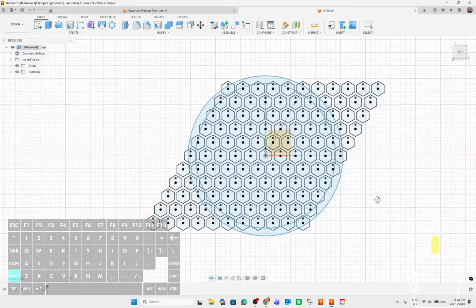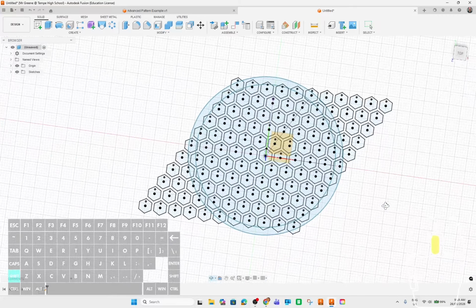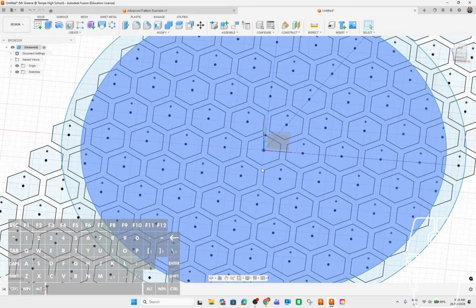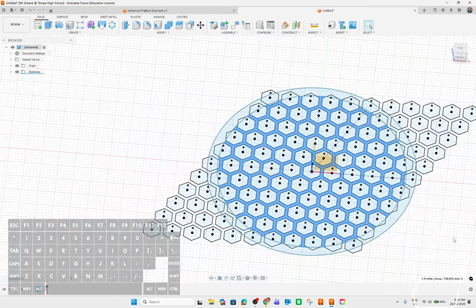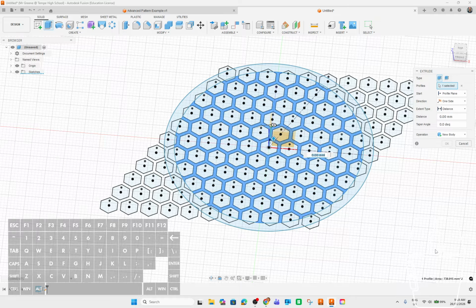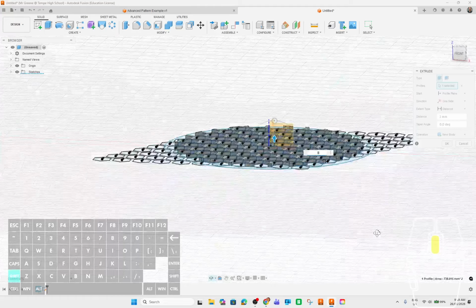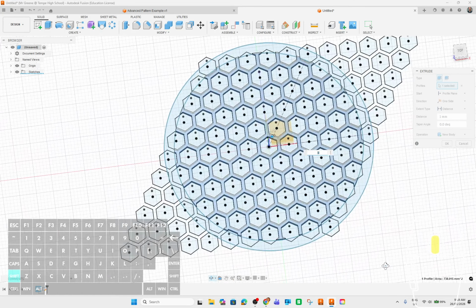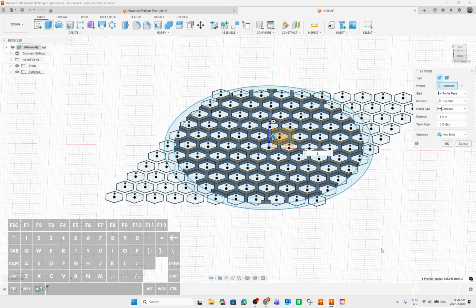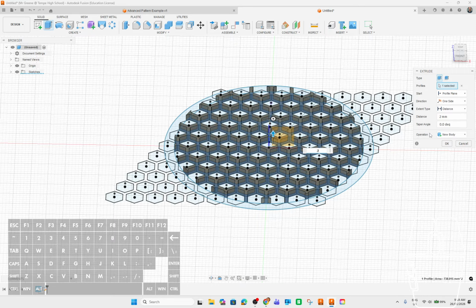You can put this inside any shape. You can constrain it any way that you want. So the first step on making this mesh will be to go to that first shape that we picked out here. All right, and I'm going to hit Extrude. And I'll put this up to 1 millimeter. Okay, so that's going perfectly inside that circle, up to 1 millimeter. I might make it 2, just for laughs, and that's pretty much all I need to do. It's a new body. I'll go okay on that.